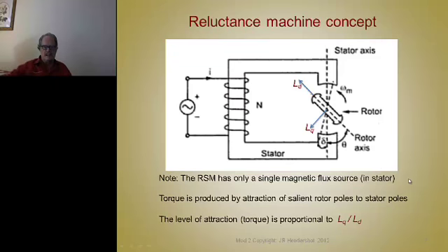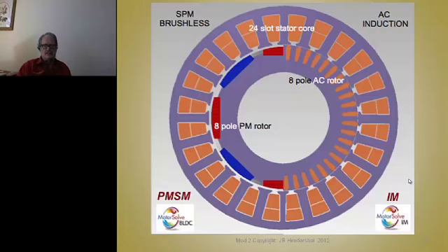So this next slide, we're going to conclude this lecture with, not the series, this lecture, this slide, which is quite interesting. How this started is we had a consulting job where we had a client. I think we designed this client. We had a motor, an 8-pole brushless motor. You see the north, south pole, and a 24-slot stator, and of course the coils are wound from pole to pole to create the same number. It's an integral slot winding.